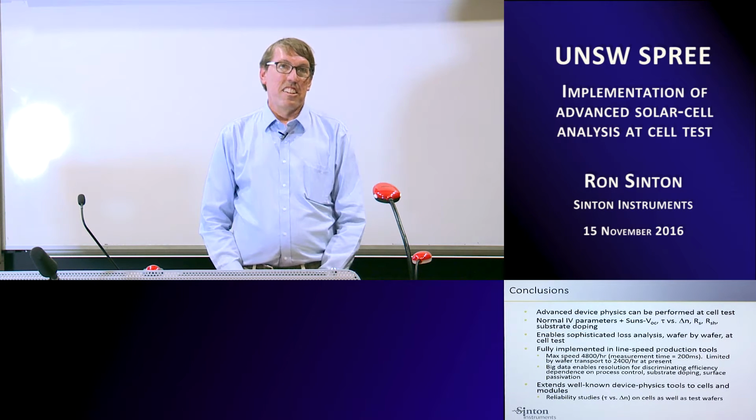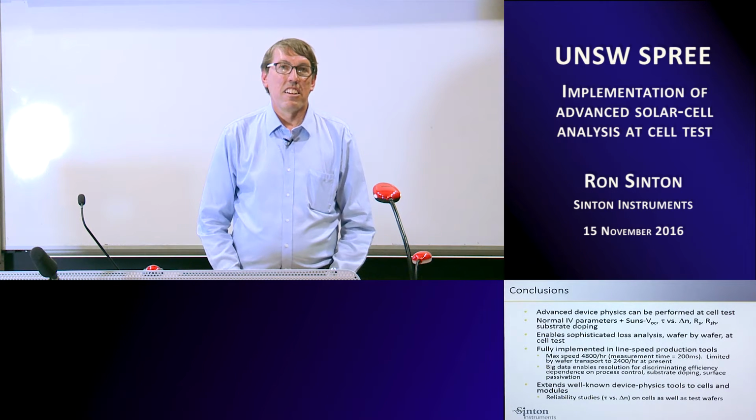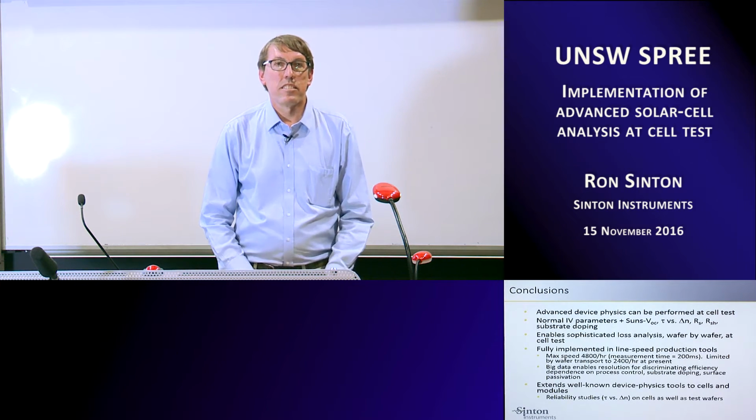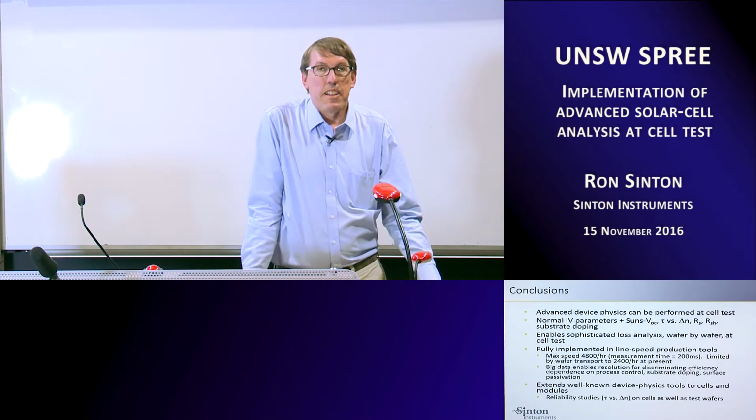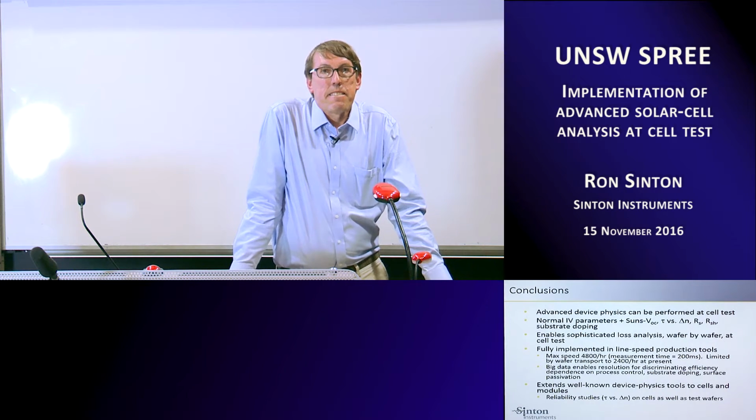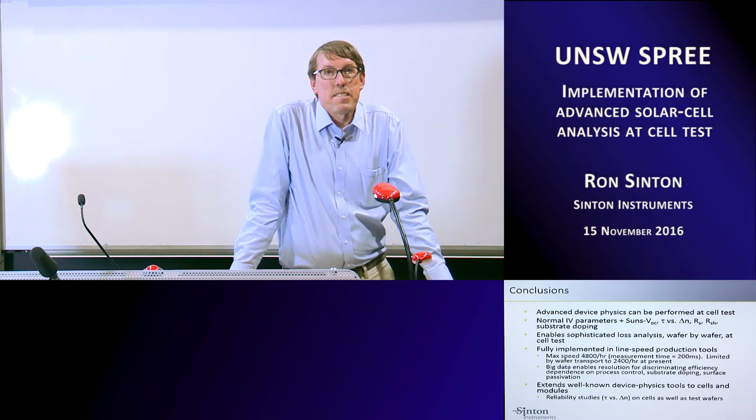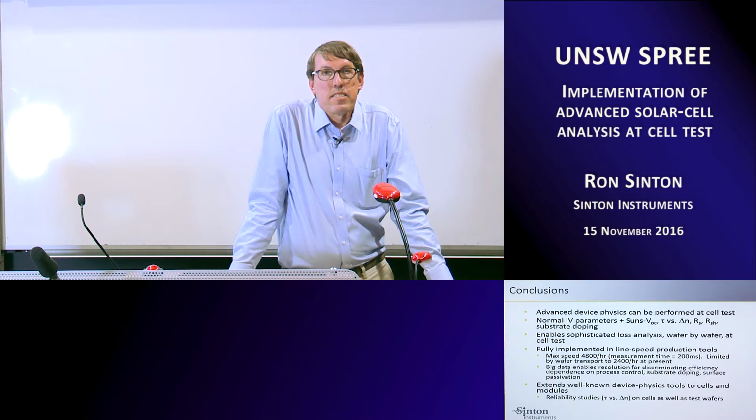Ron, I also have another question. To the capacitance measurement, or like to avoid the capacitance in the IV measurement, couldn't you just use the phase shift that comes directly out of the rising and falling arc of the flash data, and just say the phase shift is directly related to the capacitance and just do a mathematical fit to compensate?